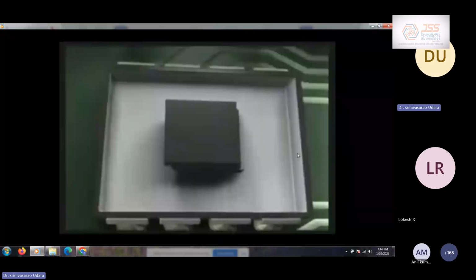The core of the MEMS accelerometer is a central mass that moves in response to a vehicle's acceleration. This inertial mass is mounted on a hinge or spring that limits its movement and returns it to a central position when at rest. Sensitive electrical sensors in the chip read the mass's movement and relay this data to a connected microprocessor. The microprocessor monitors the state of the accelerometer at rest and in motion.